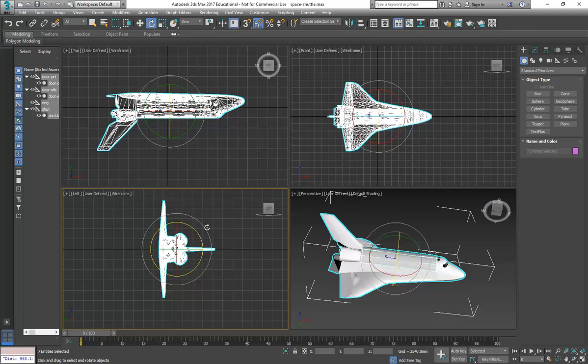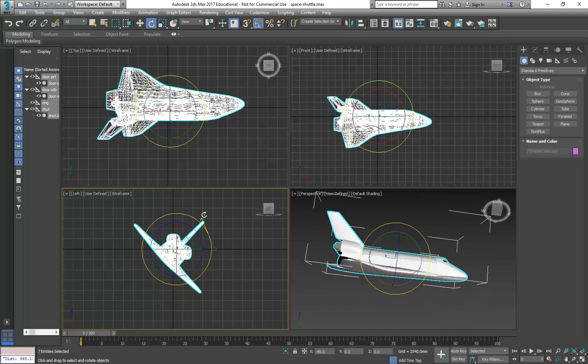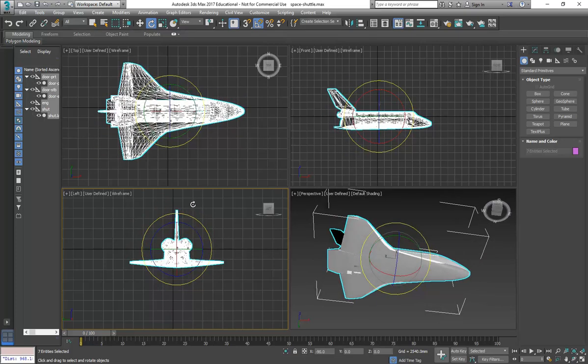And then using the grey circle on the outside is often the best way to start with rotate if you're not sure. And so I'm going to click and drag on that grey circle and rotate it 90 degrees. If you're wondering where I'm reading that, it's down on the status bar at the bottom. You can see it says -90 down here next to X.